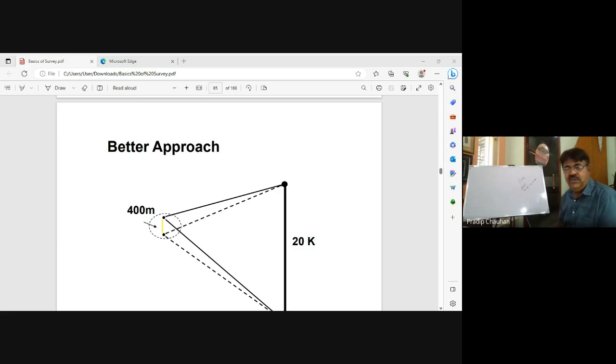The entire terrain will be divided into plain terrain, rolling terrain, and then hilly terrain. In hilly terrain there are a lot of restrictions. You cannot implement all the restrictions given for plain terrain in a hilly area. The reason is that in plain terrain, your radius of curvature for, say, 80 kilometer per hour might be 600 meter or 800 meter or 1200 meter, as IRC specifies. But then your curve has been restricted in order to achieve that speed.